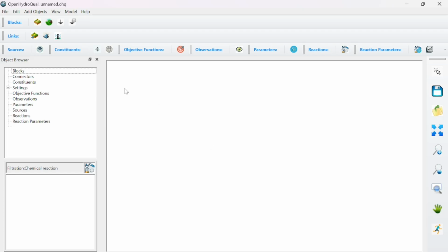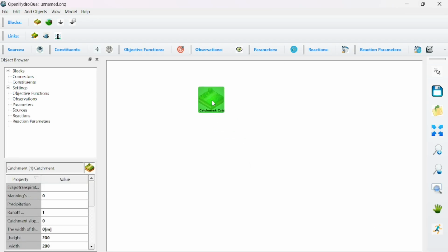So what I'm going to do is add my catchment. Actually, here's what I'm going to do. Let's say you're interested in seeing how much peak flow reduction you'll get with a pond. So I'm going to make a pre-developed condition, and then in parallel, I'm also going to create a model that represents the system after the implementation of the pond, and then I want to do some comparison, right? So the first thing, I'm going to add this catchment. Actually, let me make the pre-developed first.